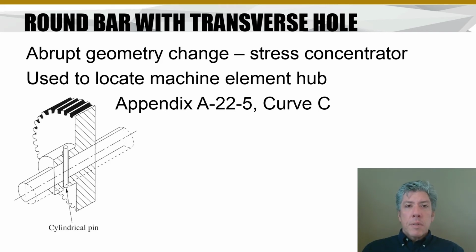Now, a lot of times this sort of design happens when you match drill an element to the shaft. So what happens is you install the element where you want it, clamp them together, and just drill.